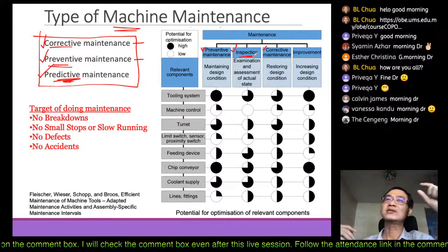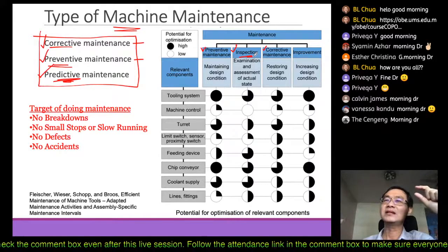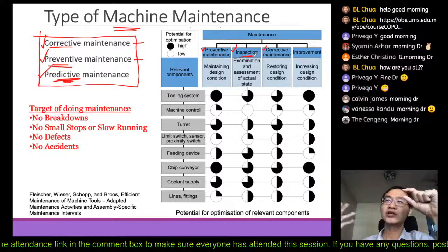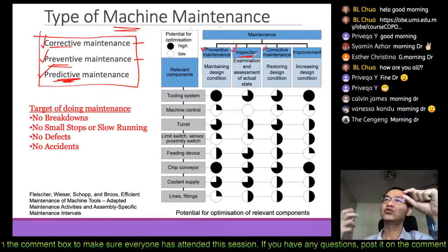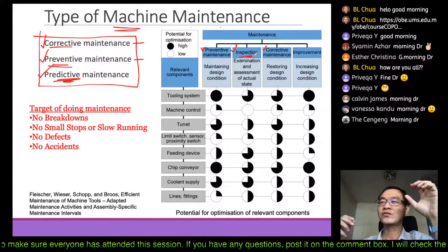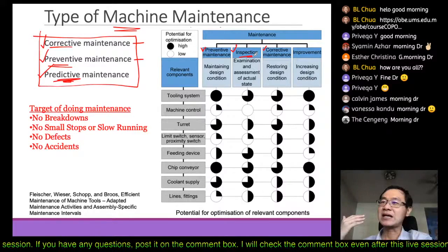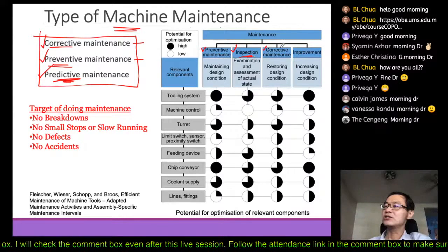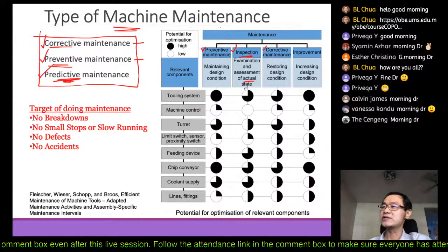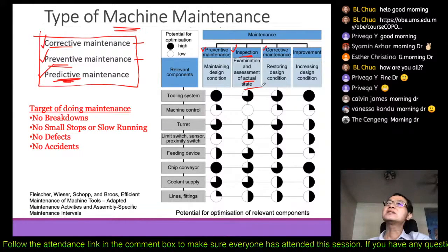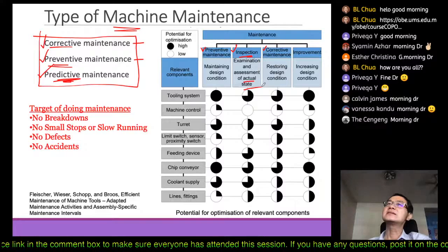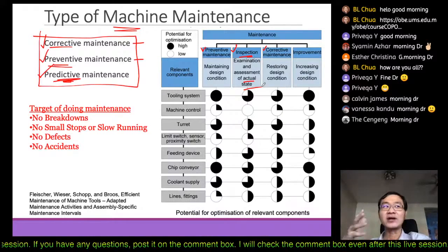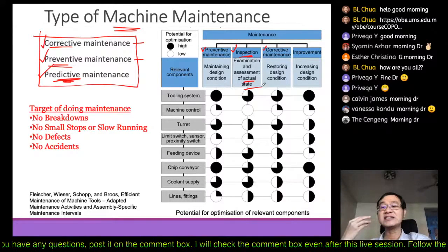For example, starting at 5 millimeters depth, or 1 centimeter depth of tread, but then after 3 months it becomes 2 millimeters depth. So from there you can estimate how much longer it can last. That is the kind of predictive maintenance. And usually with predictive maintenance, you want to assess the actual state of it. We would use this to replace or maintain components that are easily accessible, for example your wheel, where it is easy for you to monitor the status.